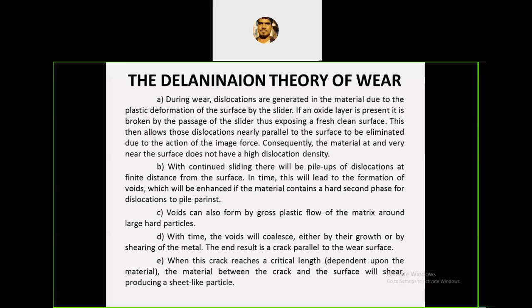First, it will reduce the diameter and increase the length. That is one thing. Second, a small crack will propagate, and that crack continuously decreases the diameter. Is it correct? Ultimately, if you increase the load, it will fracture with a cup and cone arrangement in the case of mild steel. Correct? Before fracture, it will heal plastically. It means there is one small point of a crack that is the source of the failure. Is it clear?